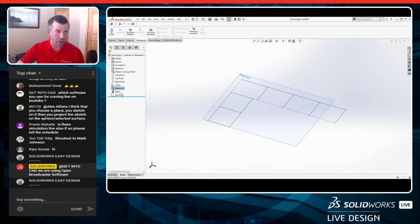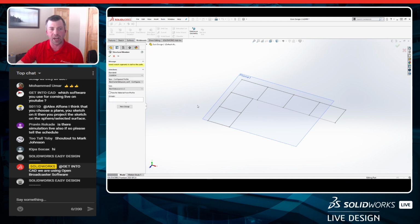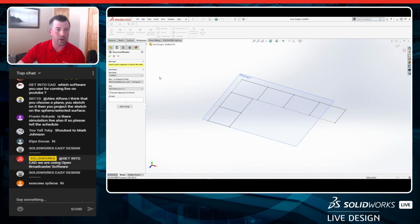Now I've got Weldments on, and that's going to enable that. And this also gives me now the ability to start creating some structural members. And this is kind of the main beauty of the Weldments tool. Now you'll notice in my library, and your library will be somewhat similar, I've got some custom cross sections in here. I've got like 80-20 that I've added in on my own. And we've got some other standards like ANSI inch, ANSI metric.